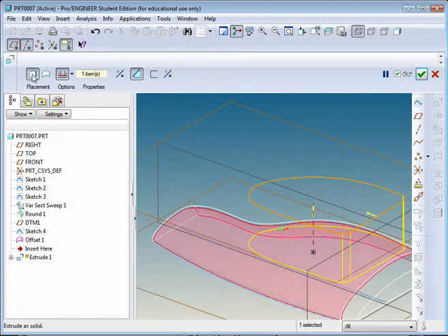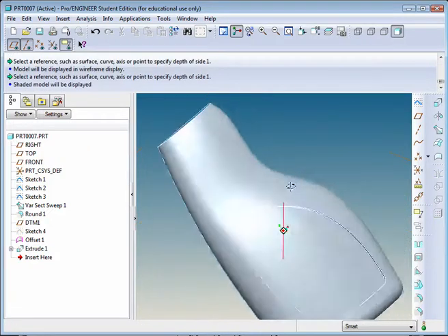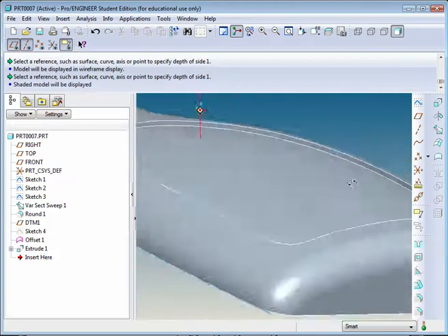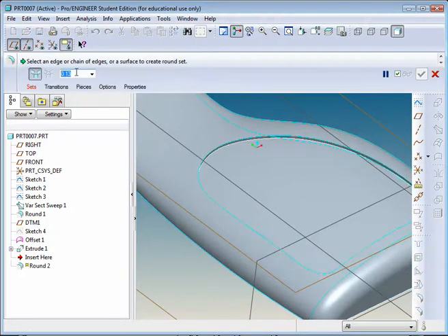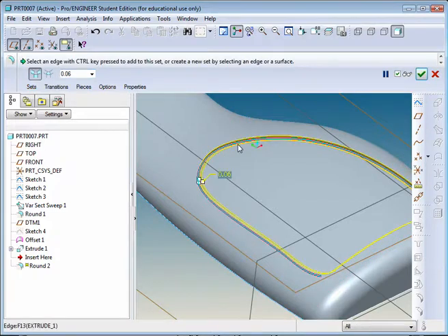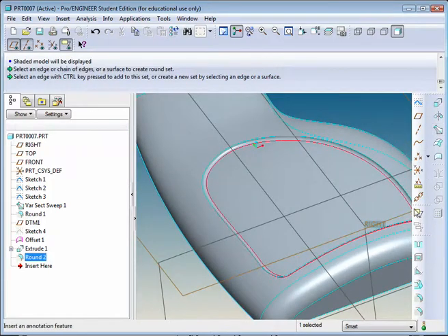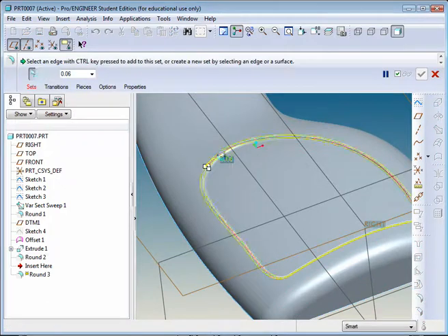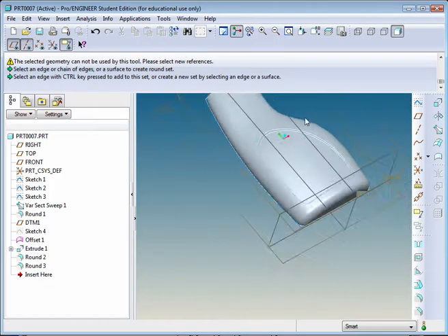Okay, with that surface selected, make sure you select solid instead of surface, as well as the remove tool. You should see a preview like this, and hit apply. And then if we go back to the shaded mode, we can now see we have a recess of 60 thousandths. Let's go ahead and fillet that and make sure that the radius is set to 0.06. And we can see our preview. Select it one time for the inner edge, and then we'll add one more round on the outer edge. And that's how you could create your label recess.